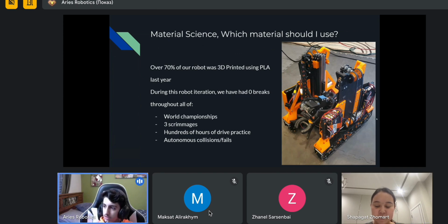Yeah, so I'll give a few examples. One of the more recent ones is, for example, our transfer. When we were first working on it, we had issues with sometimes the pixels falling out of our intake, right? Our transfer and intake are connected to each other. So our intake flips up, and sometimes the pixel would come out of that intake. It actually happened mid-competition, when we were in a match. And so we had to figure out a way to just drive without having the ability to have two pixels in at once, right?